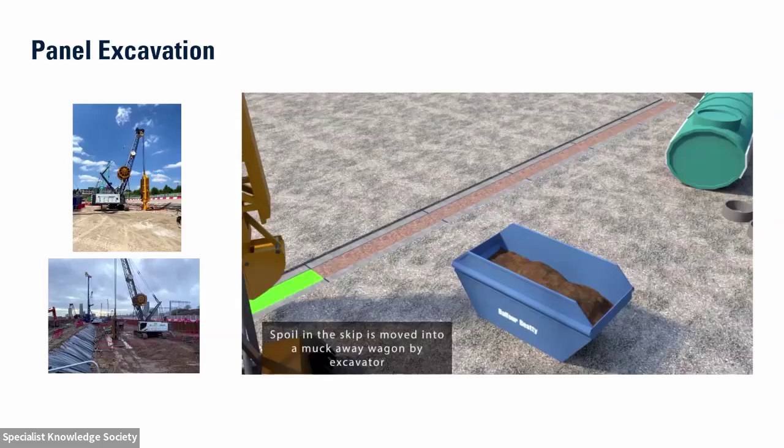You need to be able to construct your panels at that kind of width as you build the wall. And so that does influence the reinforcement design, or any propping design that you may have linked to your reinforcement. You can't say, well, let's have a 6 metre panel or a 5.8 metre wide panel around the wall, because from a constructability perspective, that's very difficult to achieve.